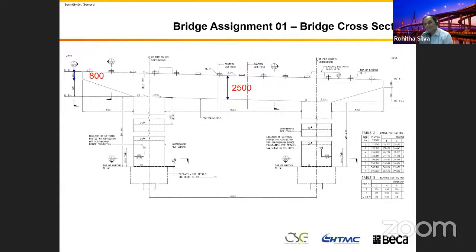If you get this design, this is your concept for the bridge. You can build this without footing, because this structure is more flexible. As I mentioned, your rock is about 20 meters below the ground. You can have a flexible structure. Because of that, you can have a single pile without footing. You can save money in your footing.